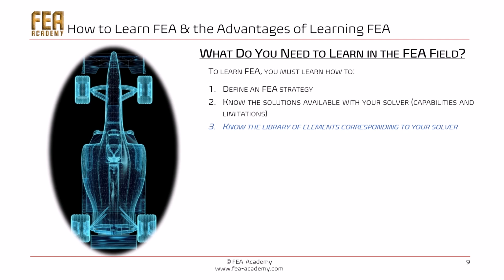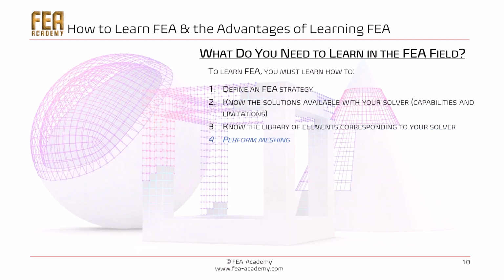Personally, when I change my FEA solver, the first thing I do is to read the documentation related to the library of elements in order to know the capabilities and the limitations of each type of element. Then you will have to learn how to perform meshing. The global FEM to capture global effects or detailed FEM to capture local effects. It is something fundamental that you have to learn.